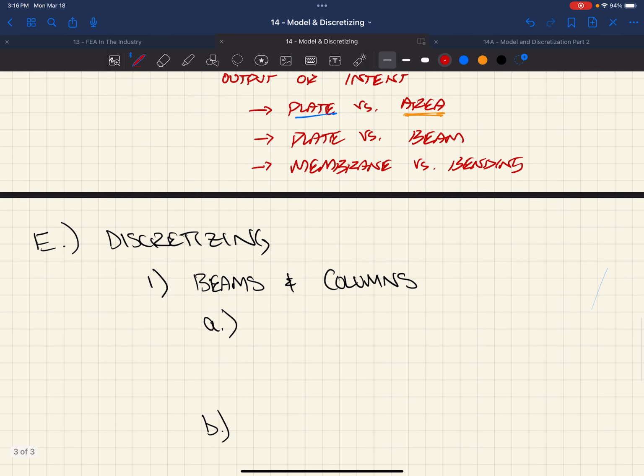So discretizing, right? Now we're gonna break everything up. This is a really big deal. This is where you got to put some thought into it. One, because depending on what you decide, the number of elements, we might just say, and some of you did on the first homework, we're just going to use the maximum amount of elements I can possibly use because I'm limited by the educational version.